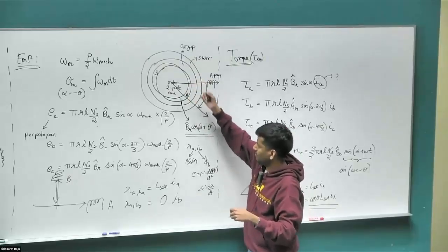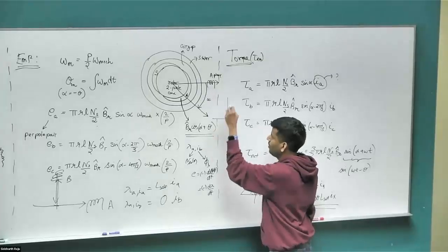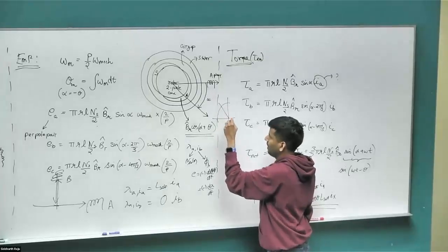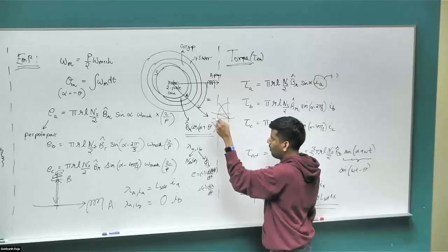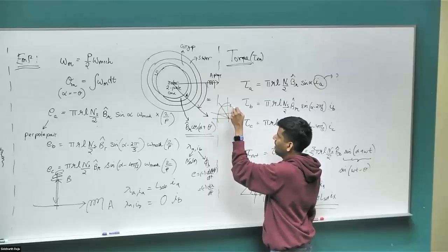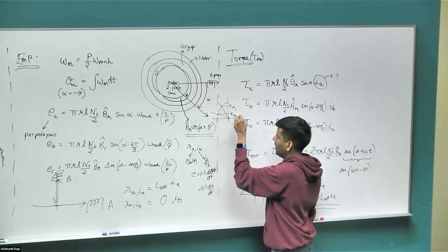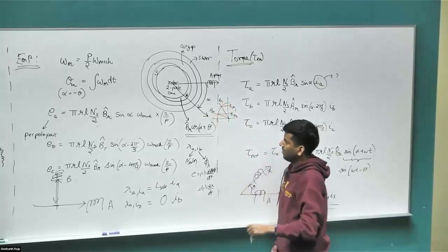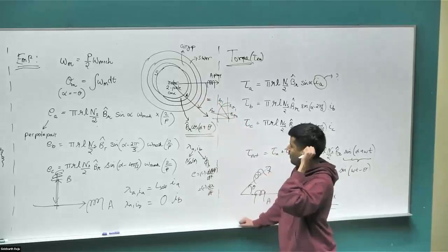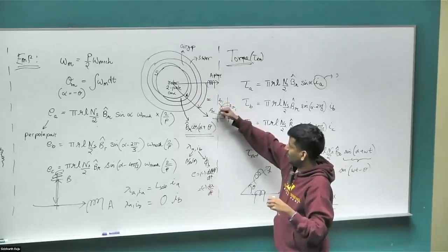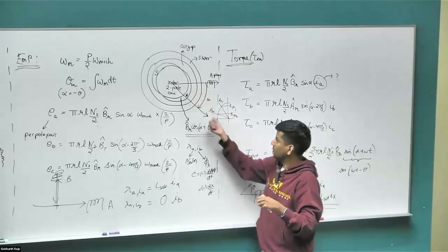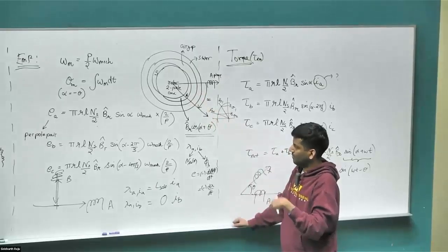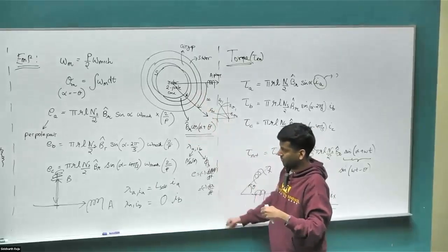Farther out, the air gap is larger, and we can make use of the BH curve, where a larger air gap makes the load line go way down. So we can get different values of B field across the air gap just by increasing LG1, LG2, increasing the effective air gap length. As the air gap length becomes bigger and bigger, we get lower and lower magnetic field, giving it a sinusoidal shape profile as well.